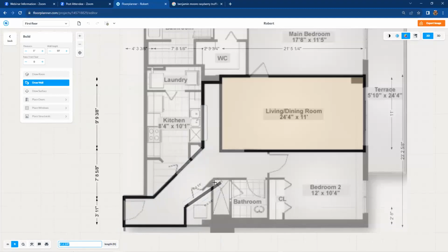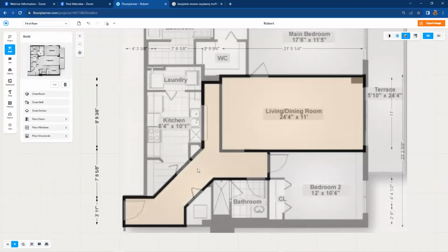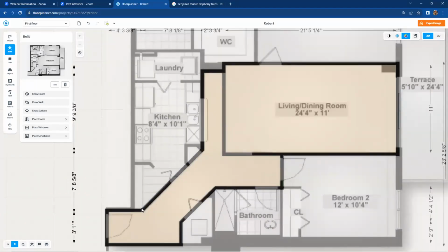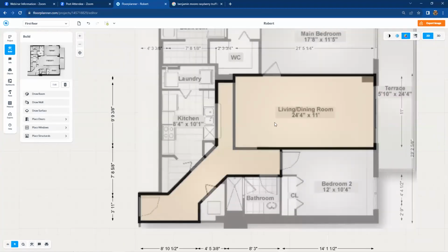And click. And follow the angle again to the intersection and rejoin. There we go. And now we close the circuit, which gave us that beige color inside there, meaning that I have a closed circuit of walls, which means with the beige area, I have a floor and I have a ceiling, everything's successful.